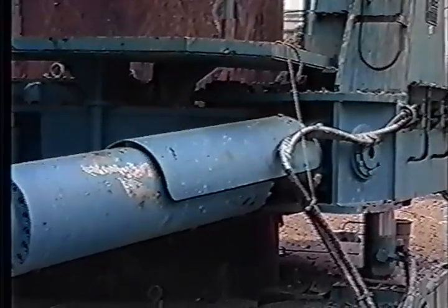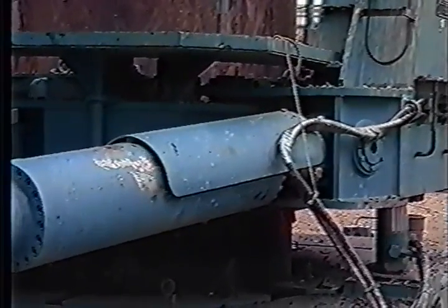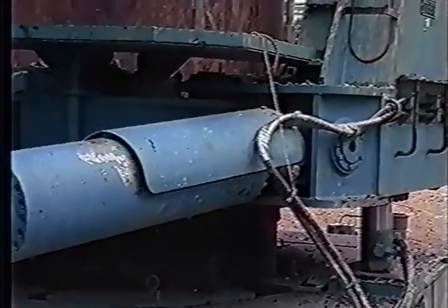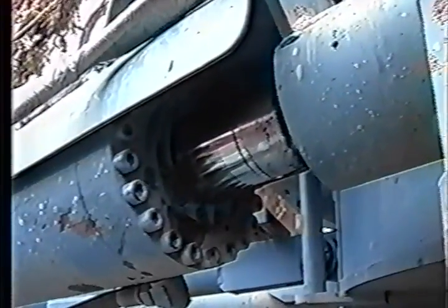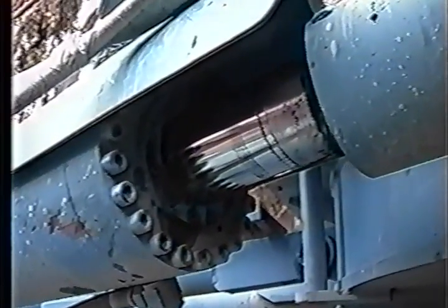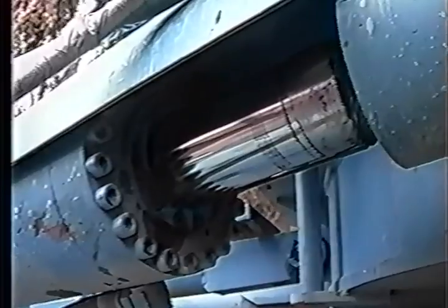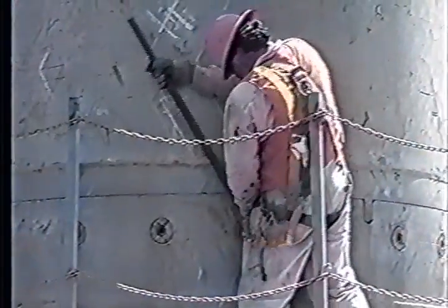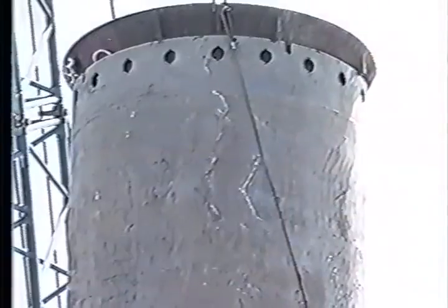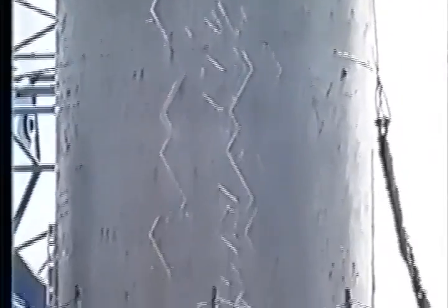The collar rotates 20 degrees in alternating directions. The casing is pulled and twisted into the ground by hydraulic jacks with torques of up to 6 million foot-pounds. Drill casing is available in lengths of up to 8 meters. During the drilling, sections of casing are joined by tightly fitted collars with inset conical casing screws. The wall thickness of heavy-duty drill casing ranges between 40 and 60 millimeters.